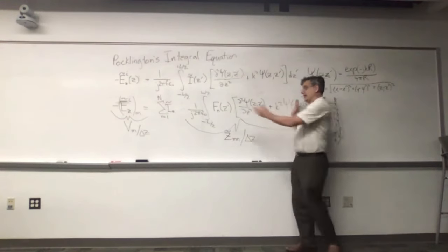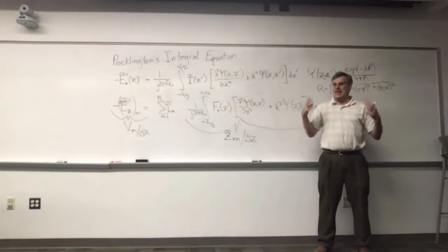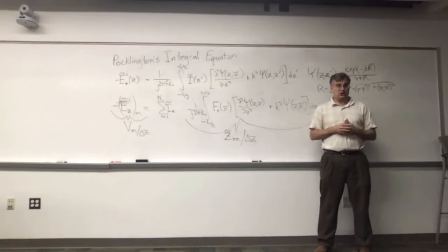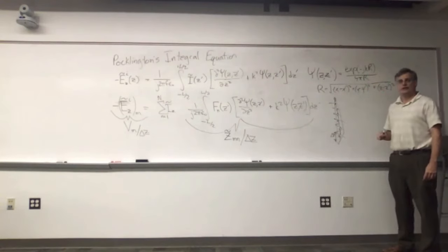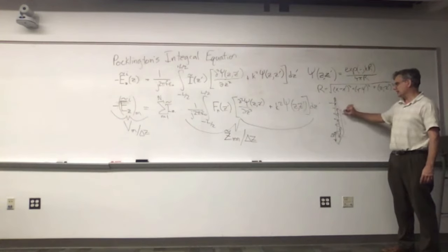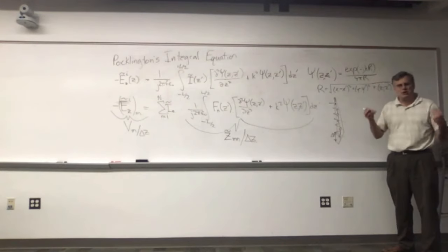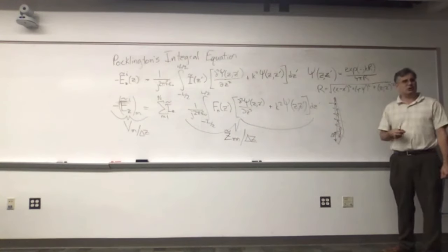So this integral expression will have n squared different evaluations, because I have 7 possible locations for my E field to calculate, or my voltage, and all 7 currents contribute to that. And none of them in quite the same way, unless we have a geometrical accident of symmetry.